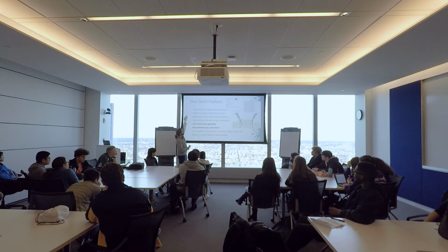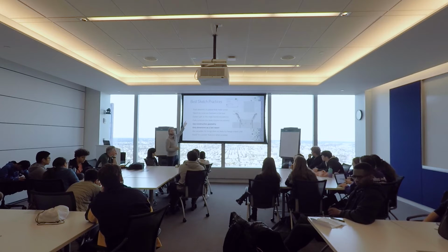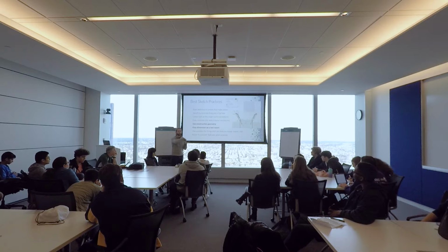Generally, you want to try to minimize features in the tree, as I mentioned before. So you want to try to do as many things with as few features as possible. There are some exceptions to that, but that's the general trend. You also want to center the part on the origin for the most part. Like with your robot, the dead center of your robot should usually be the origin, the point at which you would rotate with a tank drive. You can do it differently, but then you have to consider your center of gravity calculations for that as well.